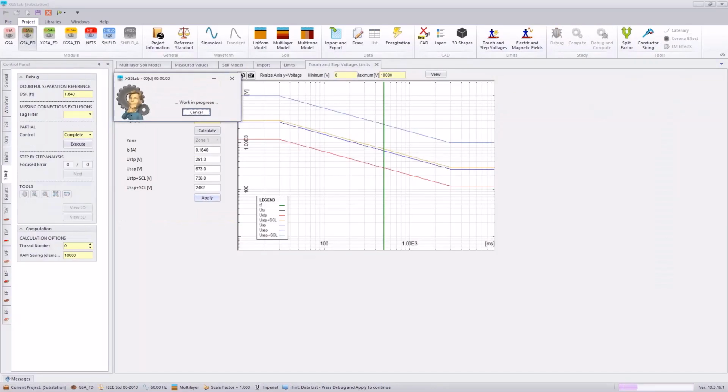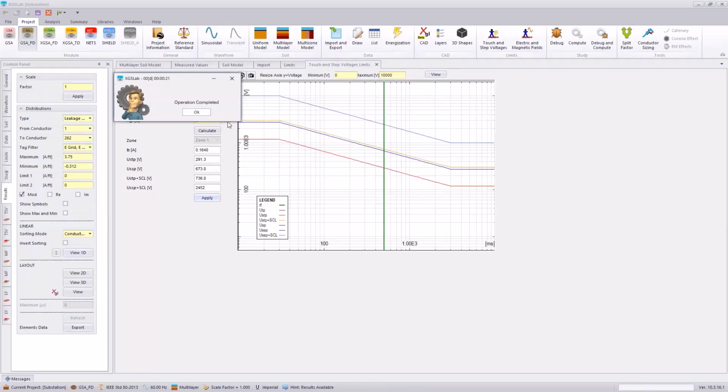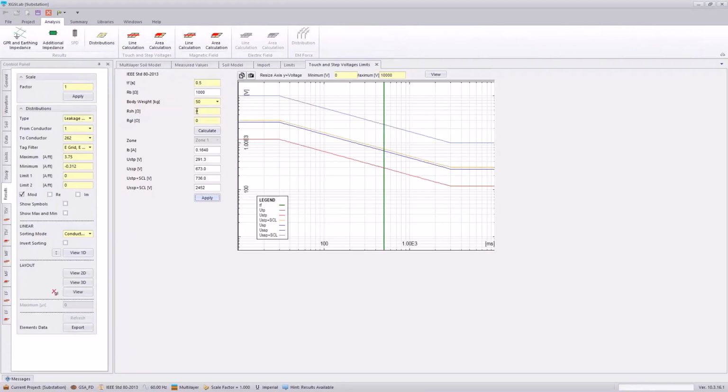And what this is doing now is actually calculating the ground potential rise based off of the grid resistance or the impedance that's calculated from the software. And we will take a look at the potential of our grounding system and the potential of this tank that has just had conduction through the soil. And we are going to do this case example.